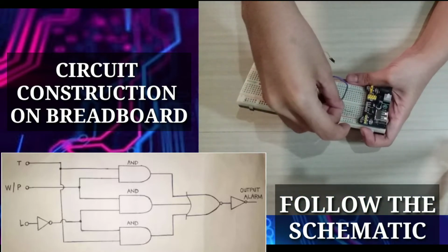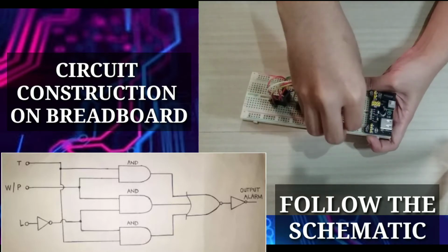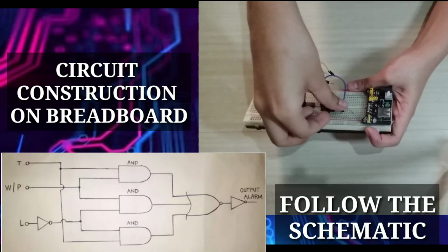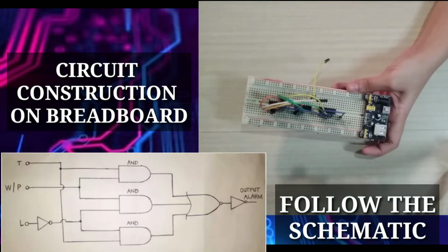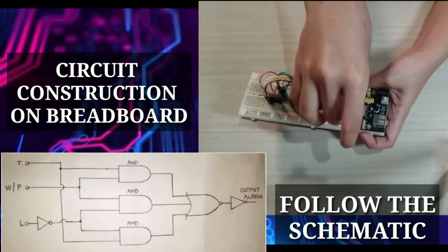Don't forget our 360 ohm resistor so that our LED will not be shocked when it lights up. And for our output, we will be putting our LED in series with the resistor.